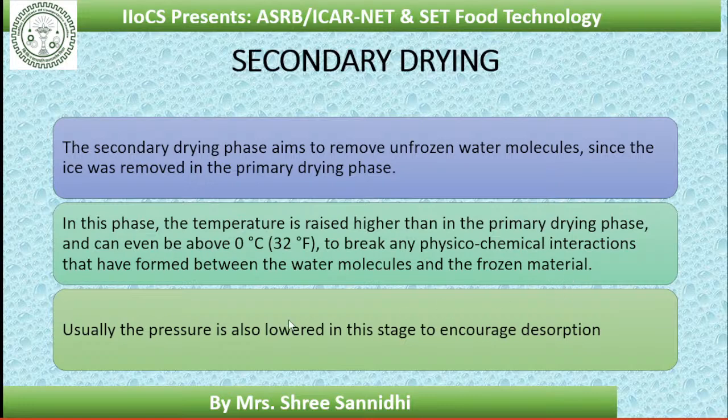So as I told before, if there is any physico-chemical interaction, that is the bound water molecules, then a little rise in temperature will allow the water molecules to break the bonds and then to sublimate. Usually the pressure is also lowered in this stage to encourage desorption.